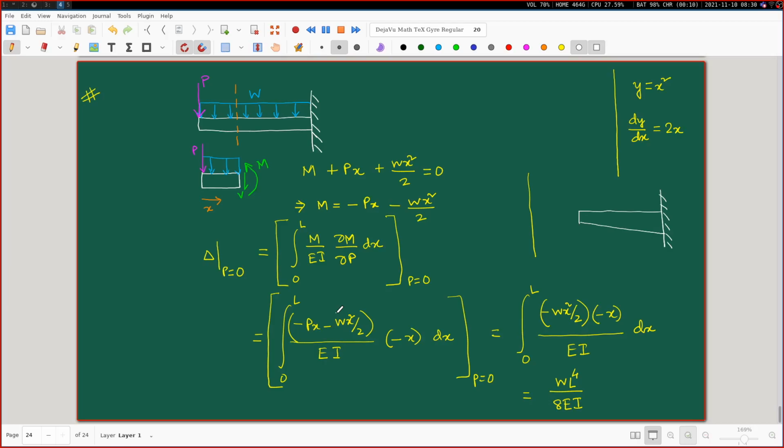Nobody is going to force you to solve it by the deflection method or by the energy method. But I can tell you one thing: once you learn the energy methods, it is very hard for you not to use them. It is very, very tempting to use energy methods all the time. In fact, there was a suggestion yesterday that even if you have to determine the deflection as a function of x, it is still possible to use the energy methods to determine that.